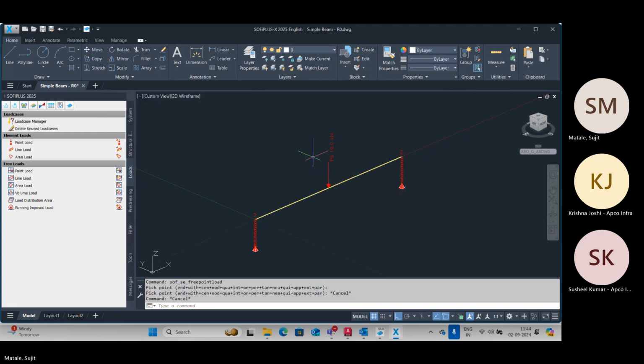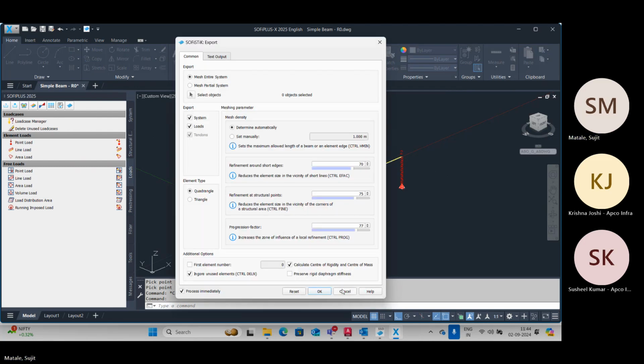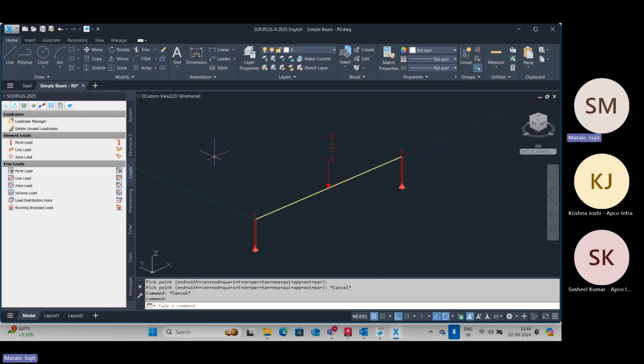Okay. So we will get into the depths of this. Okay, what free loads are, what element loads are, why point load under element load, why point load under free load. We will discuss all this. But there is only one load case to be assigned, the self-weight case. It should be automatically considered based on the unit weight, the cross-section area, and the volume, which it calculates on its own.